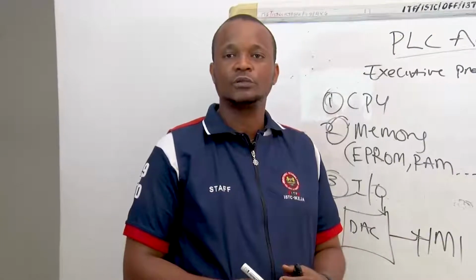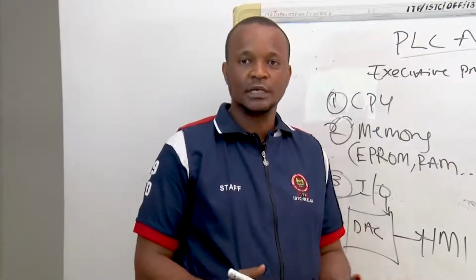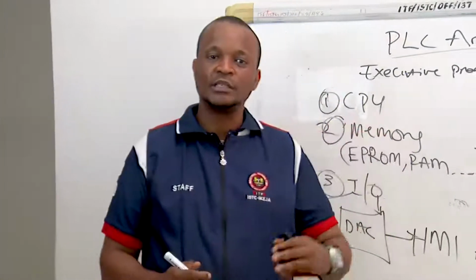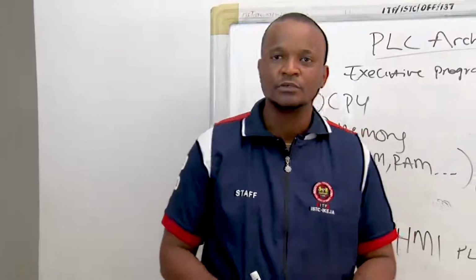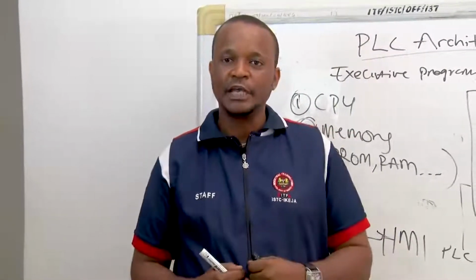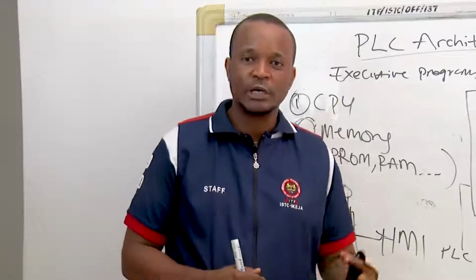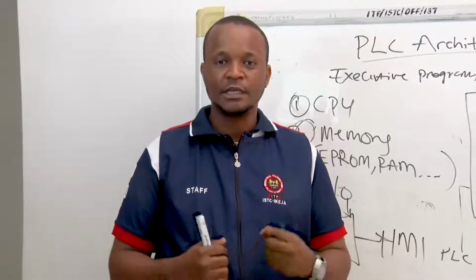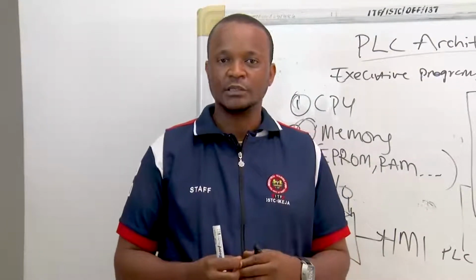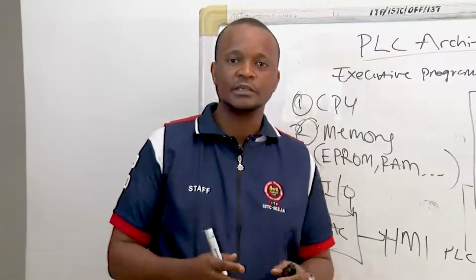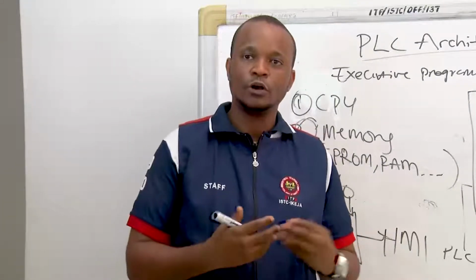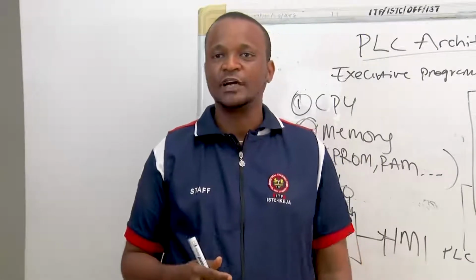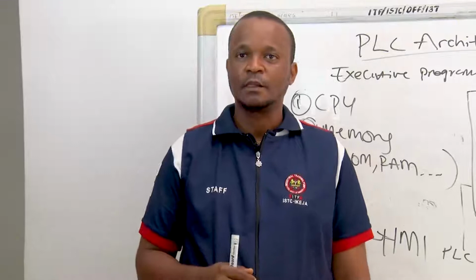The PLC also contains things like input relays. This is the superior function that the PLC has over the traditional relays. So you can call up virtual relays in the PLC. You can call up virtual counters. You can call up virtual timers in the PLC. These are contained in the PLC. So instead of getting real-life relays, most times you can call up the countless virtual input and output relays that you can find inside the PLC, okay?